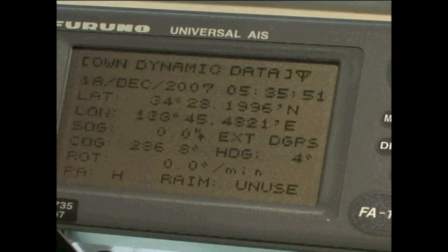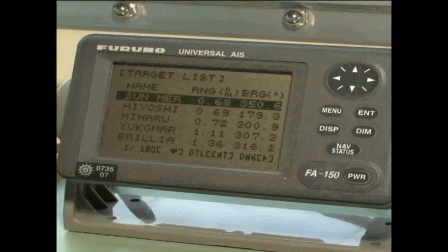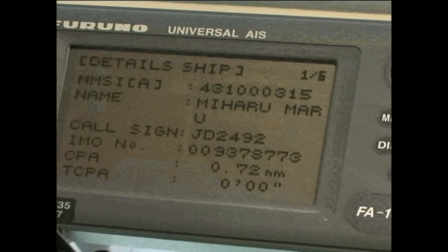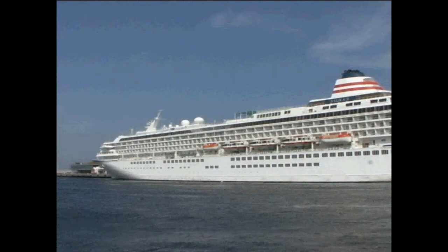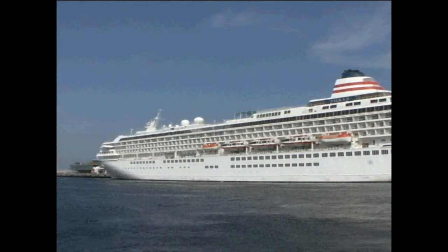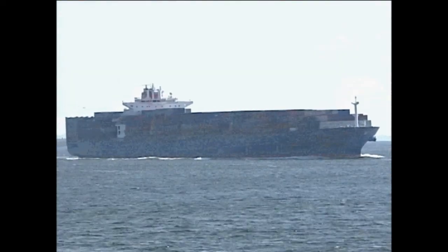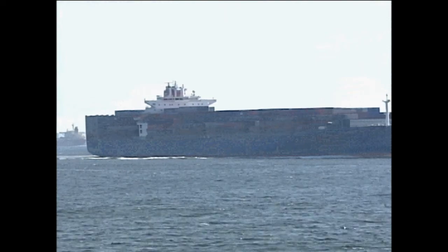Using the VHF band, the AIS periodically transmits navigational information, such as the position, speed, and course of own ship, the ship's name and cargo. It also continuously receives and displays similar information received from other ships. Under the SOLAS Convention, all passenger boats, ocean-going cargo ships over 300 gross tons, and coastal cargo ships over 500 gross tons are required to install AIS.